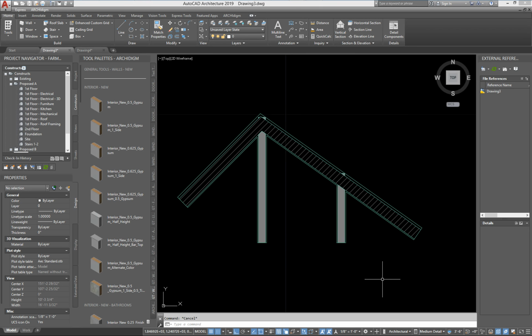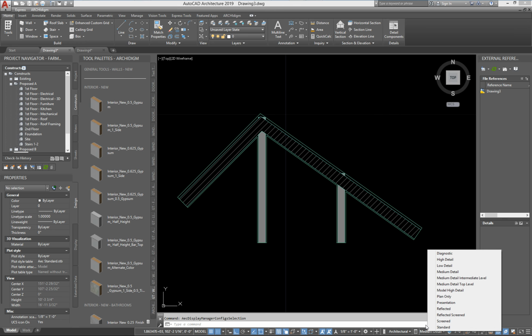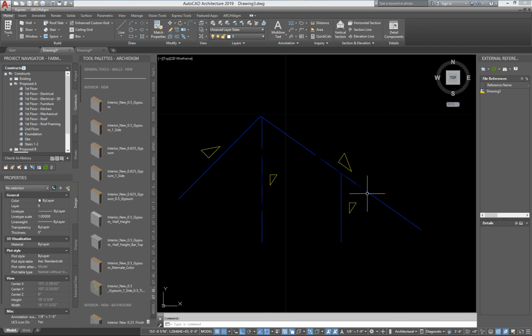Now, what I can do here is I can go and investigate. I don't need to because I know what I can do, but let me show you how to start investigating scenarios like this. We'll go to the diagnostic, and what we'll see is the baselines of the walls and how they're intersecting. These baselines want to connect in order to do a proper cleanup. Otherwise, you have to work with something called the cleanup radius, which is a circle that reads out and finds the next closest baseline to work with. So, well, we can do it here if we want to.